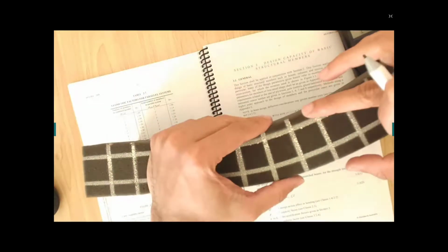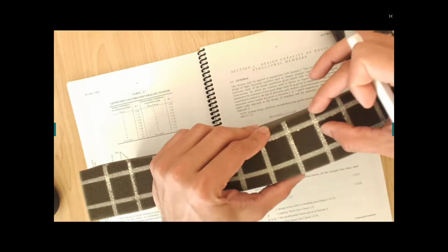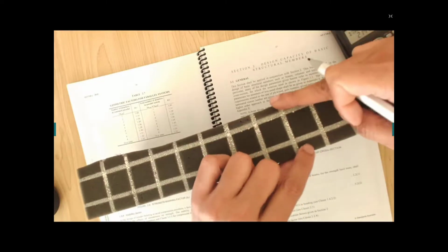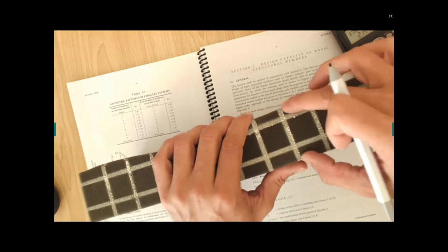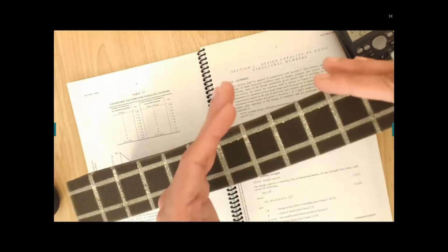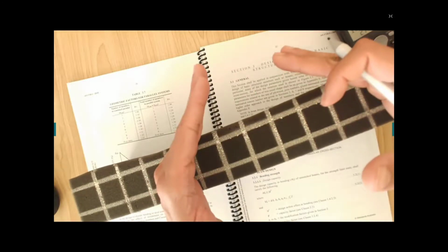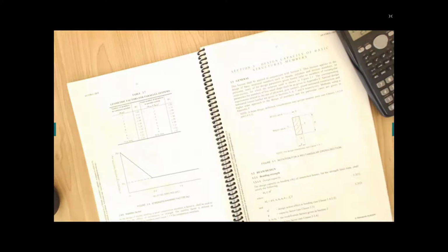Bending stress is equal to the moment that I am applying, times distance y from the neutral axis where you want to calculate the bending stress, because that's the point where you experience the largest bending stress, over I. And I is just BD cubed over 12, the moment of inertia, the resistance of the beam due to the geometry of the beam, right? That is known to you. That's fundamentals. Every engineer should know that bending stress is My over I.